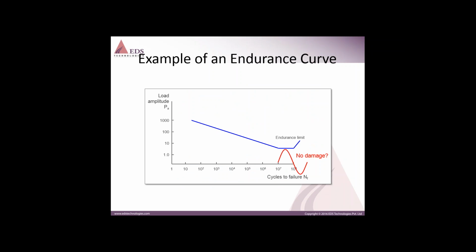If we test a steel specimen in air, our damage curve looks something like this, whatever we can see on your screen. And load amplitude you can see here, and life is on the horizontal axis, and you can see that both of them are on a log axis.